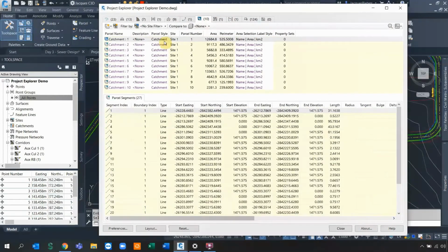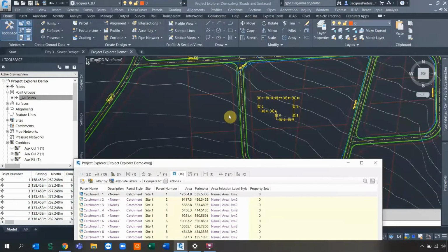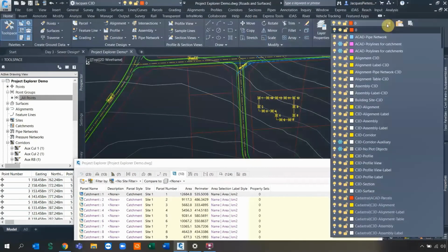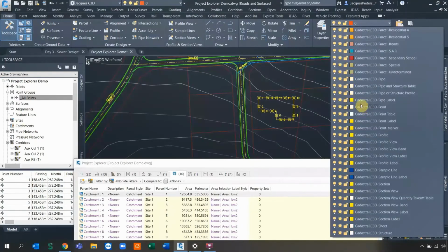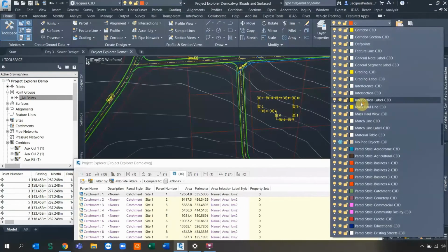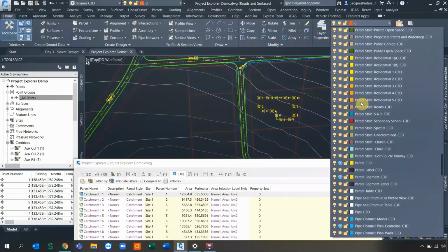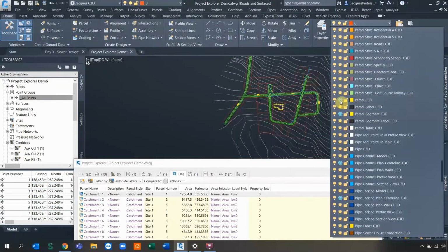Then you also have parcels, so you've got more control when it comes to parcels. Under parcels, we can define them. For example, I did hide mine, so I had catchment areas inside. Let me switch them on in my layer properties. If I navigate to those specific layers which I switched off, let me go down, down, down. I'm looking for my parcels. Oh, there we go. I unfreeze them, and there you can see it actually adds the tags.